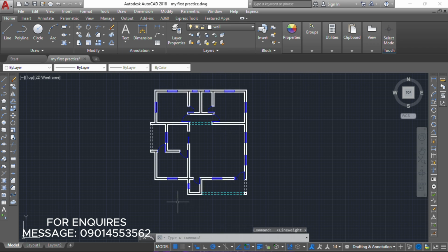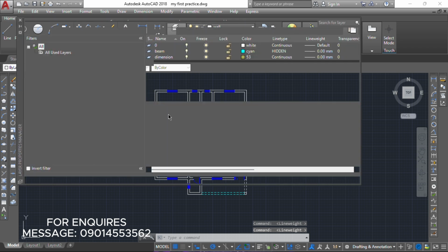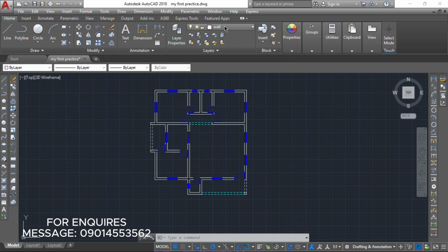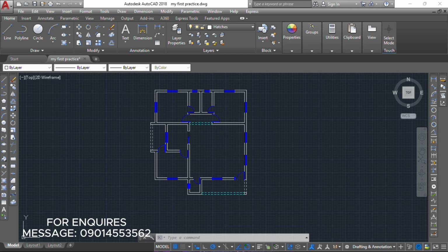So now if we should do like this, it's kind of disfiguring the design, kind of, right? But not totally disfiguring it. Let's just switch it off and create a layer for our hatch. We just need to use hatch, right? Now let's select it as our current layer, and then we can either come here to our hatch tool here or type HA for hatch and enter.